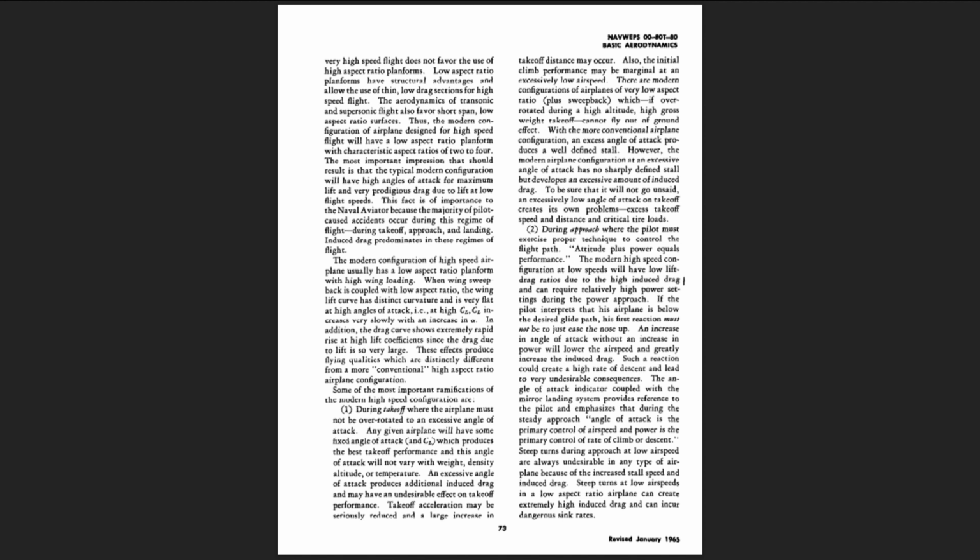With the more conventional airplane configuration, an excess angle of attack produces a well-defined stall. However, the modern airplane configuration at an excessive angle of attack has no sharply defined stall, but develops an excessive amount of induced drag. To be sure that it will not go unsaid, an excessively low angle of attack on takeoff creates its own problems: excess takeoff speed and distance and critical tire loads.